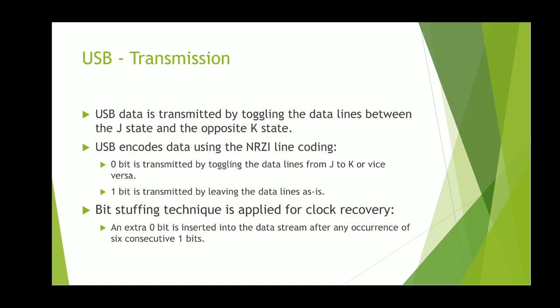And there is one problem associated with the NRZI encoding. It is that if some consecutive 1 bits occur, the data lines in the USB port will maintain their voltage level at a constant value.